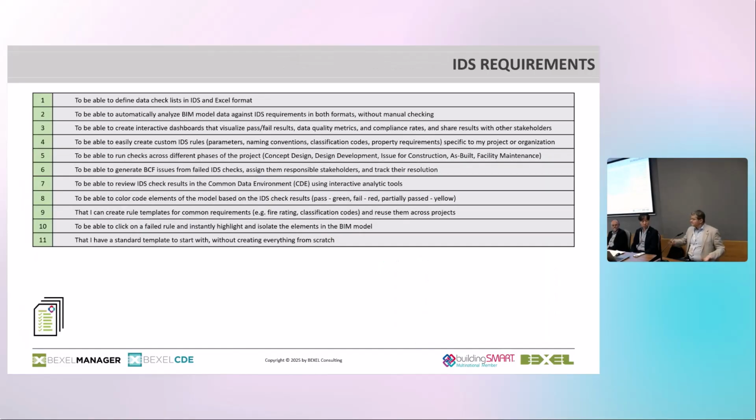With IDS, I think Scott already mentioned more or less everything. So this is really important, but I have to say, fit for purpose. My suggestion to all of you, talking now from the top management perspective: do not put 200 properties in an IDS checklist as a requirement, because nobody wants this. What I will as an owner immediately ask you is, show me all the dashboards where you use them. If you don't use them, why? You put a huge pressure on the designer or on other guys to do something you don't need. I can tell you, sometimes you need just 15.